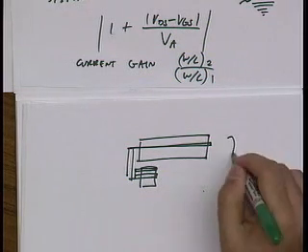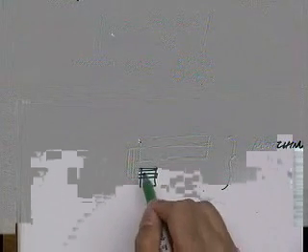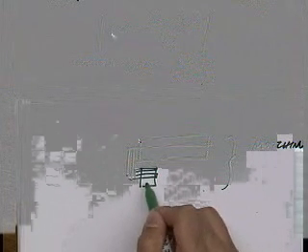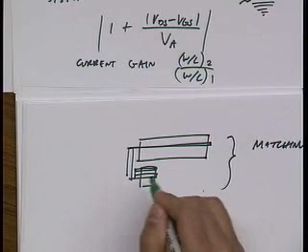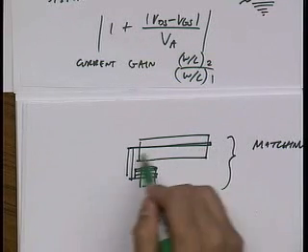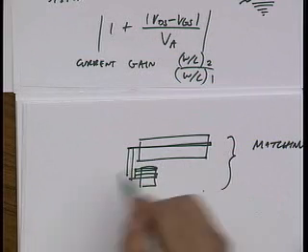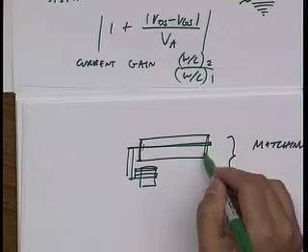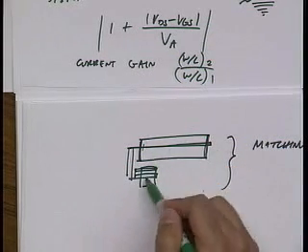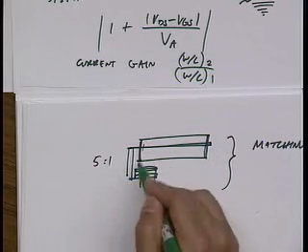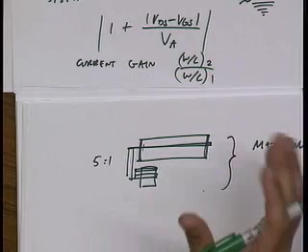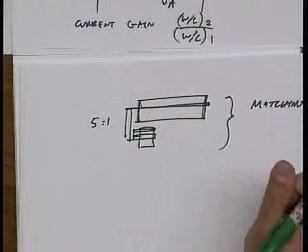This is basically going to have a systematic matching problem because this tiny device is very sensitive to lithography around it, right? So the edge effects, and it's so small, the effective W is going to vary. Whereas this device, it's wide, and so only the edges will get affected by lithography. And so you might think you're getting an integer ratio of, let's say, 5, but you're going to end up getting something different. So there's going to be a systematic error to start off with.